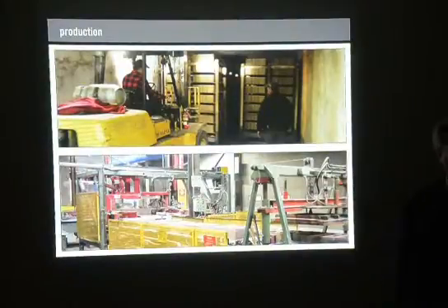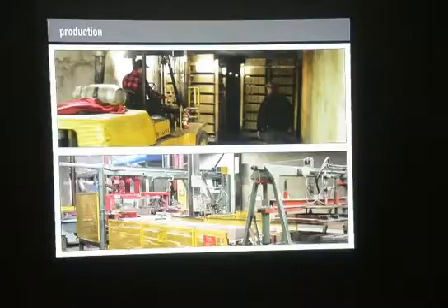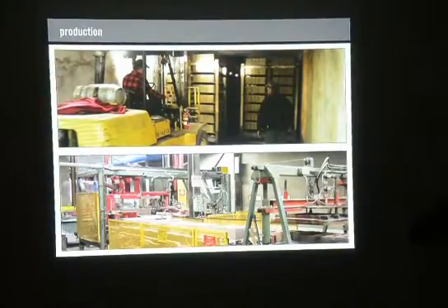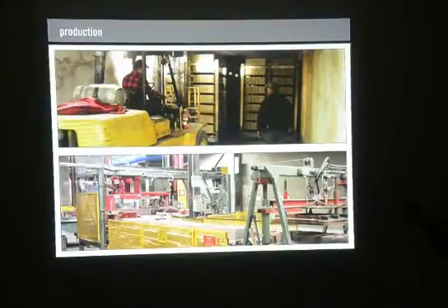And you say, well, Mike, you're 3/8 short. Well, that's true, but we have to incorporate mortar for the difference of the 3/8 to make it an 8-inch block. So it's 8 by, say, 8. So it's 8 wide by 8 high, and then maybe it's like 16 inches long, which is known as a standard block. And that's what these ones are. They're 8 by 8 by 16. Okay.